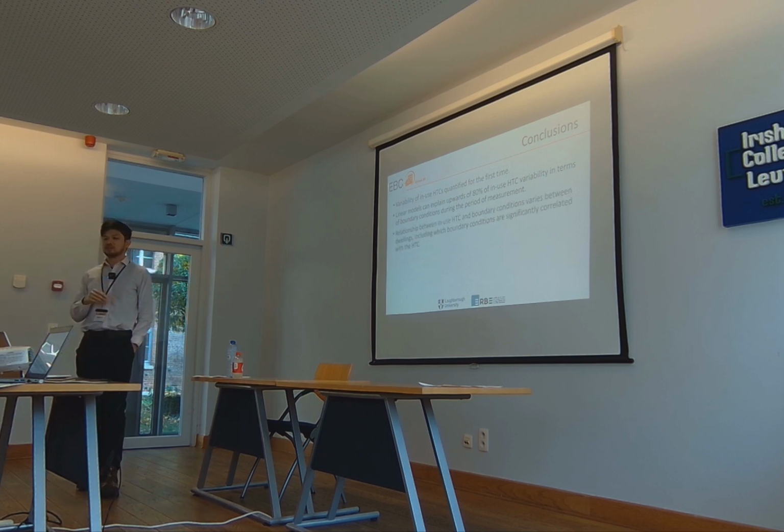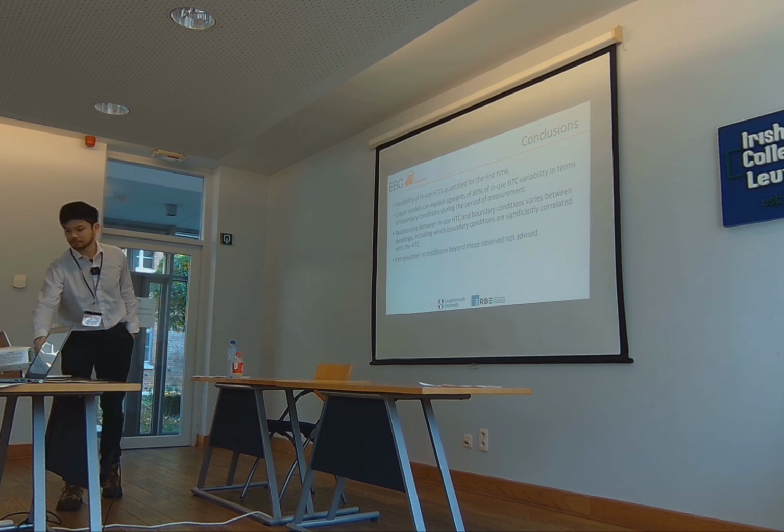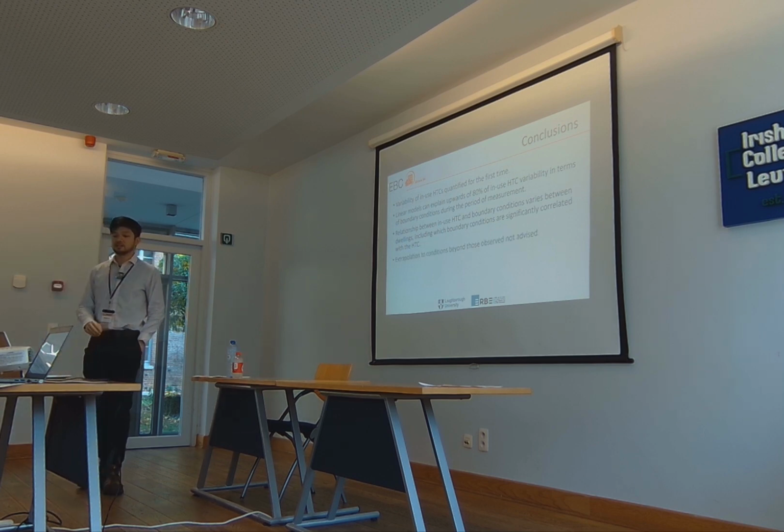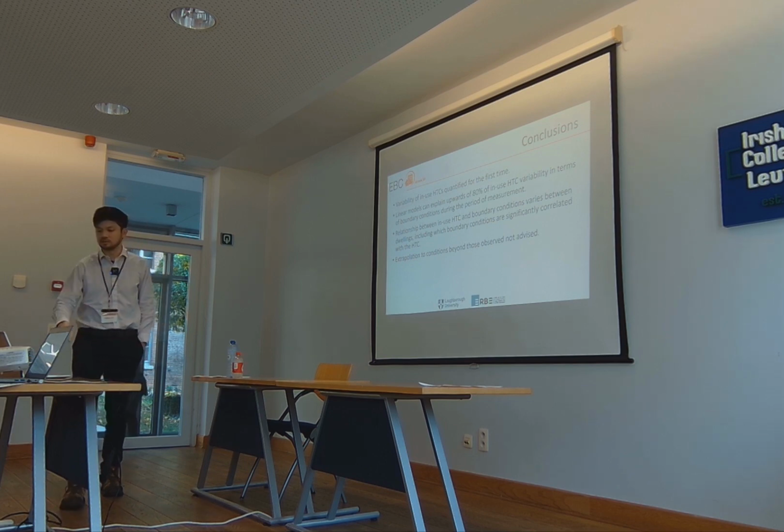and that the relationship between the in-use HTC and boundary conditions varies between dwellings, crucially including which boundary conditions are significantly correlated with the HTC. And then that final point: extrapolation to conditions beyond those observed is not advised, because we saw those poor results.